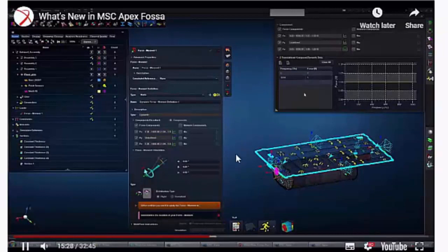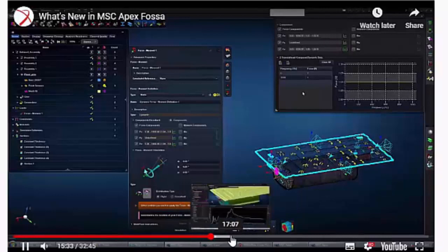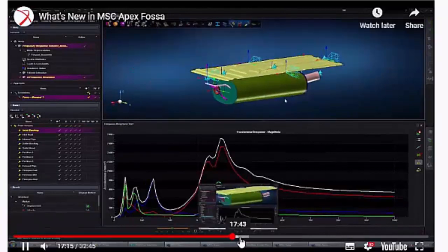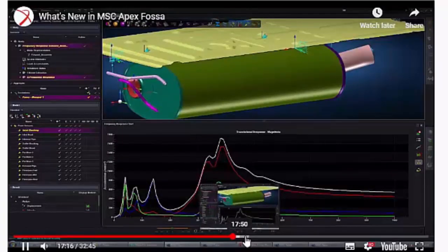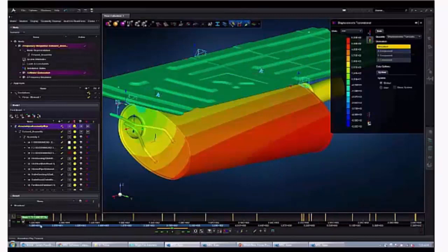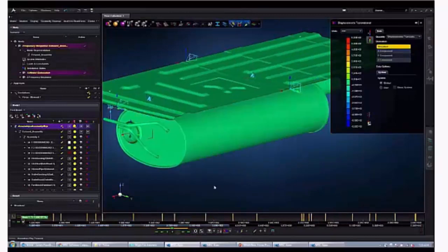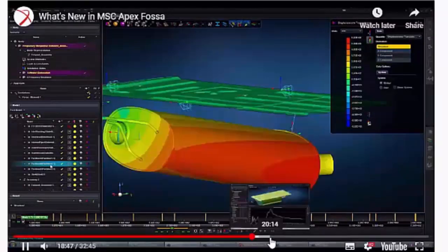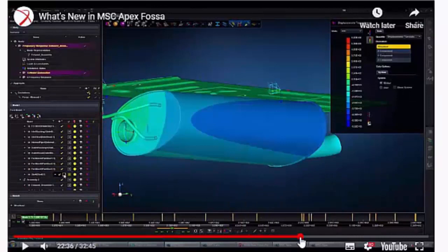So they've defined a frequency dependent input force at various locations. They've defined the sensors, locations where you would like to measure the frequency response. And what you can also look at immediately is the participating modes. So it shows you the weights of each participating mode, which you can then visualize as well. So you can actually see what the actual mode looks like.